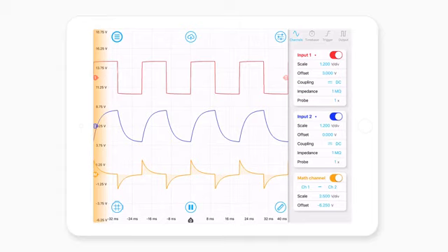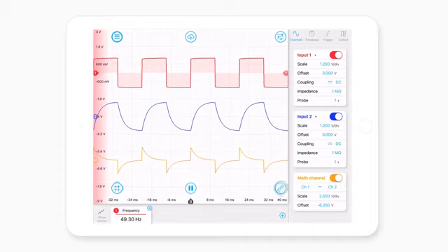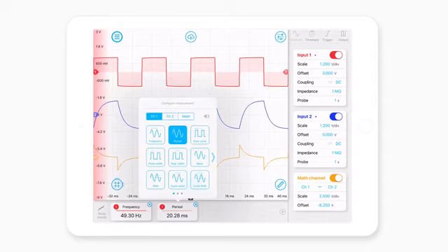One last thing here in terms of the waveform traces is if we want to quickly measure important characteristics of these signals, then one of the things that you might want to do is drag up the measurements panel by tapping this icon here and adding different measurements in. So when you hit this little plus symbol here, it will bring up a measurement specific to the trace that is highlighted. So the red trace is highlighted currently, and by adding a new measurement, it's automatically populated with the next measurement in the list. If I was more interested in, for example, measuring peak-to-peak amplitude, I would just go to the next page and tap peak-to-peak.